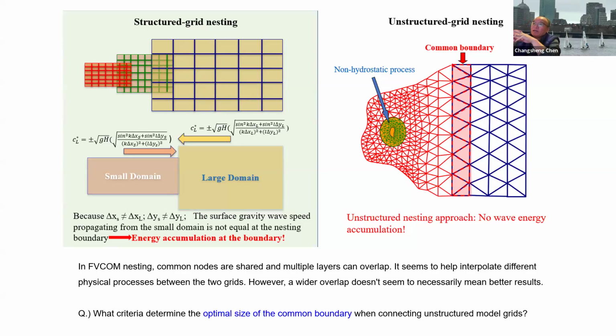What happened? That's why the wave is dispersed, right? Before it was a non-dispersed wave, but you change it numerically, and you become a dispersed wave. Energy will be lost. You see me? So this kind of dispersive wave depends on resolution. With a bigger resolution, the wave speed can be different from a smaller resolution. So when the resolution changes, the wave propagation speed changes.